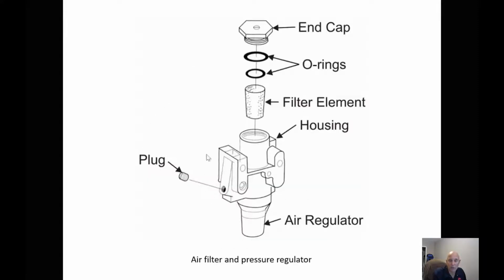If we take a look at the filter regulator, it uses sintered bronze filters, so it's pressed. What happens is air pressure comes in from our system. Now our air system might have a pressure protection valve, which means the pressure protection valve doesn't open until 90 psi. So if the air pressure drops down, we may not be able to use our range and splitter.